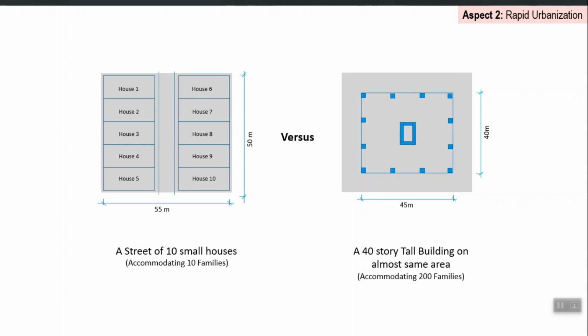So you can color code those elements within the software platform, and then you can directly tell the performance of your building to the client, and if it is acceptable, the design is okay. If it is not acceptable, change the design and do that again, and unless your desired performance objective is met, actually not desired as a structural engineer, but desired from the client side, if it is met, then that design is final, right.